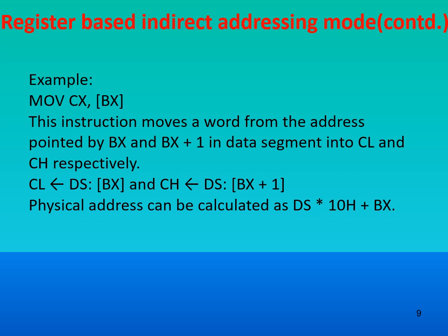So what is inside that BX? The BX contains not the value here. The content of BX will be the address now, since it is enclosed within that bracket. Find the difference. If I was just writing MOV CX, BX, the content of BX would be considered as the data, and that data would be taken directly and given to the CX register.